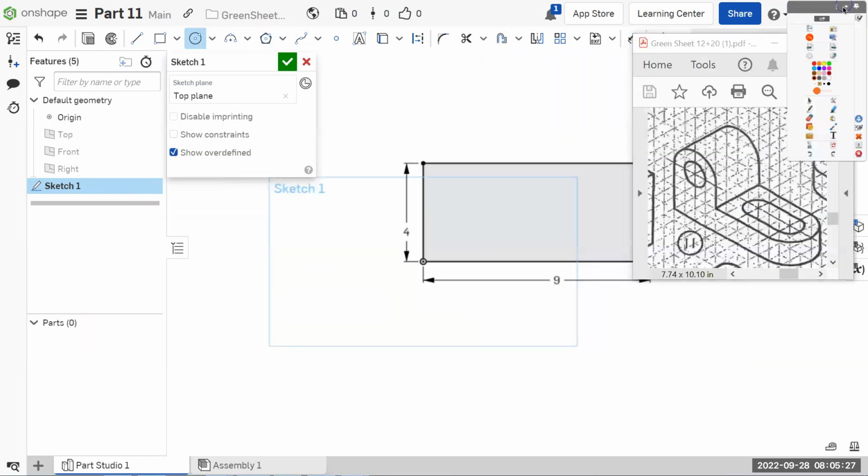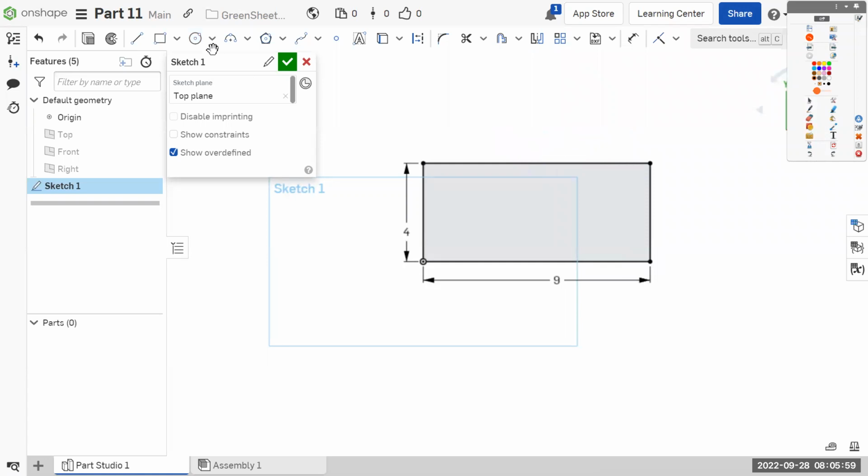And if you follow along, okay, this center mark right here, because there are these extension center marks all the way out, that means it's the center mark for this arc. It's the center mark for this arc also. So we can count from here, it's 2 this way and 2 this way. We know that the center of this arc is centered on our first rectangle, or on the short side of our first rectangle. Okay, so let's get a circle.